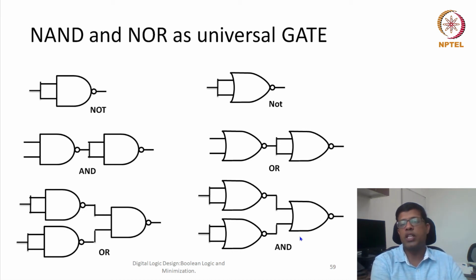A sea of NAND gates means they created a chip which has thousands of NAND gates, and because fabrication of a chip was always a costly and complicated affair, once they had fabricated these NAND gates, they used them to construct any sort of design, whatever they wanted to configure.